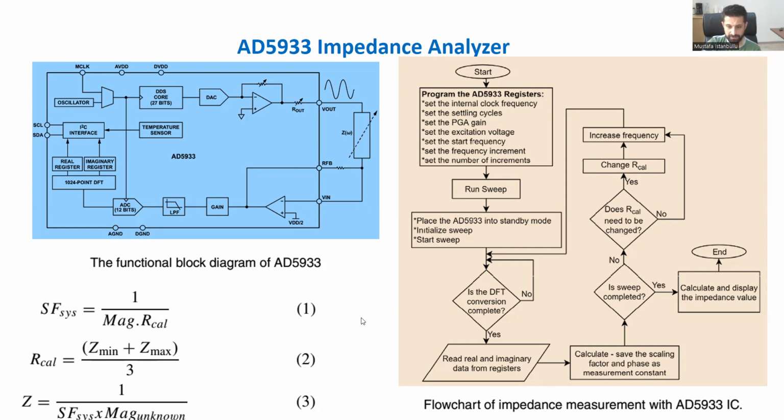Although there are many successful applications and studies with AD5933, the most significant drawbacks are the nonlinear calibration requirement and measurement error due to these calibration effects. Direct digital transfer of the measurement information constitutes an estimation problem related to analog part of the AD5933 from DDS to the DFT modules.